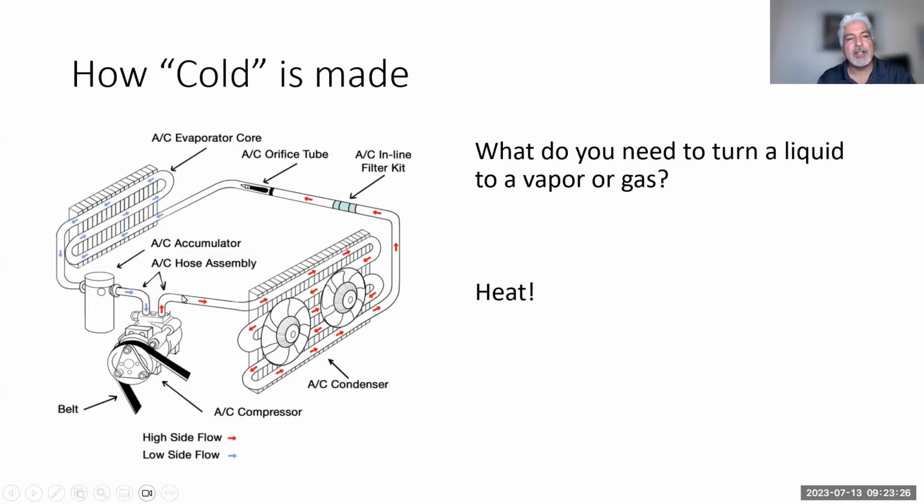So this must be the outlet as we follow the arrows. This is the outlet going out. So therefore it pushes up against the orifice tube. So if the orifice tube is totally blocked, and let's say there was contamination there, then that's going to raise your high side pressures and it'll kick out eventually with the high pressure cutout switch that we use.